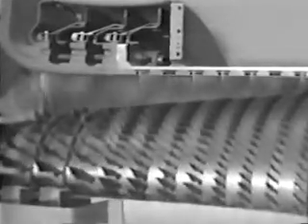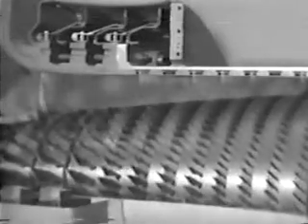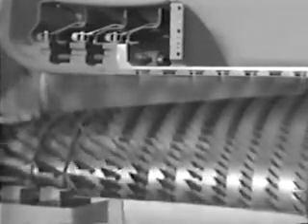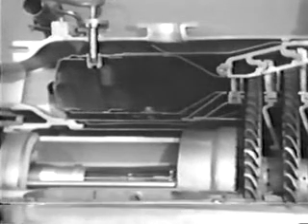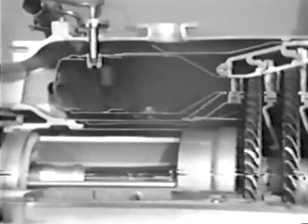In an airplane, stall makes the airfoil inefficient and lift is lost. When stall occurs throughout the compressor, airflow ceases. This condition is known as surge. When airflow decreases in the turbine engine, the combustor and turbine sections heat up rapidly to extremely dangerous levels. This will severely affect the turbine components and decrease the engine's lifetime.